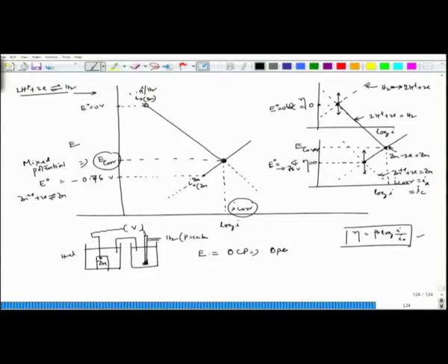open circuit potential. Remember, once we try to measure this zinc potential with a standard hydrogen electrode, initially that potential is switching from one potential to another until it reaches this potential. So, once we allow a little bit of time, we see that the potential has achieved this particular E corr, or OCP, and it is maintaining that potential with time.